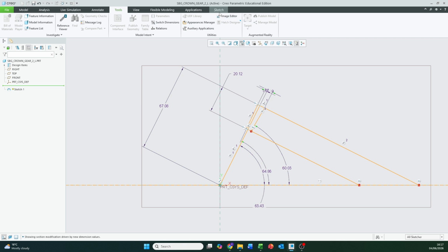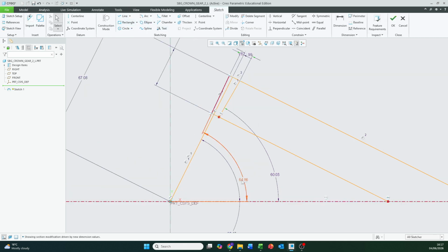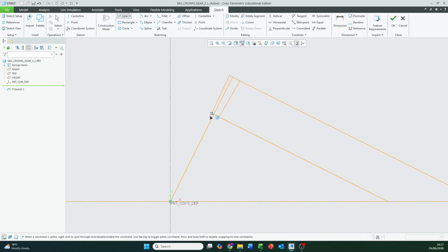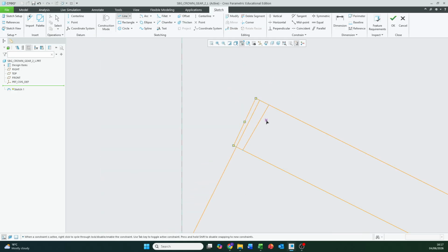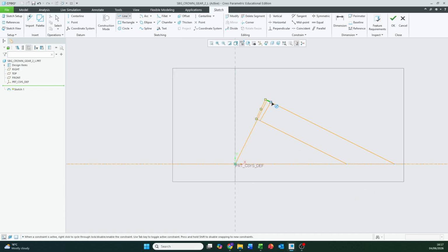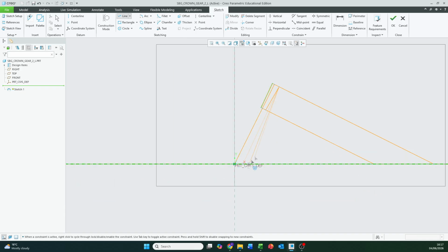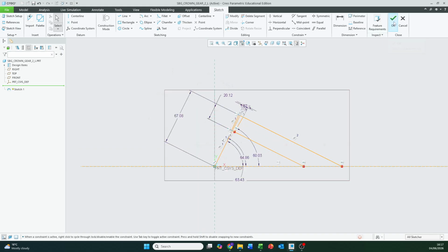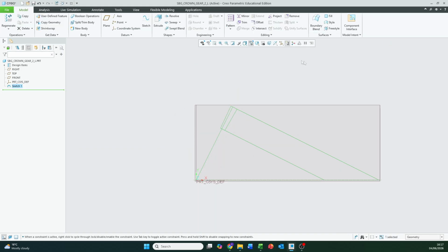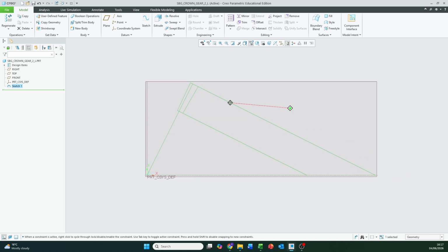Okay. One thing just to note, by the way, I know that we define all these angles through maths, but if you extended these lines out, the addendum from the tip circle and the addendum from the base circle, they do just connect to the middle anyway. But good to have everything mathematically correct. Okay. So just as with the first gear, the steps are the same, just in slightly different orientations.